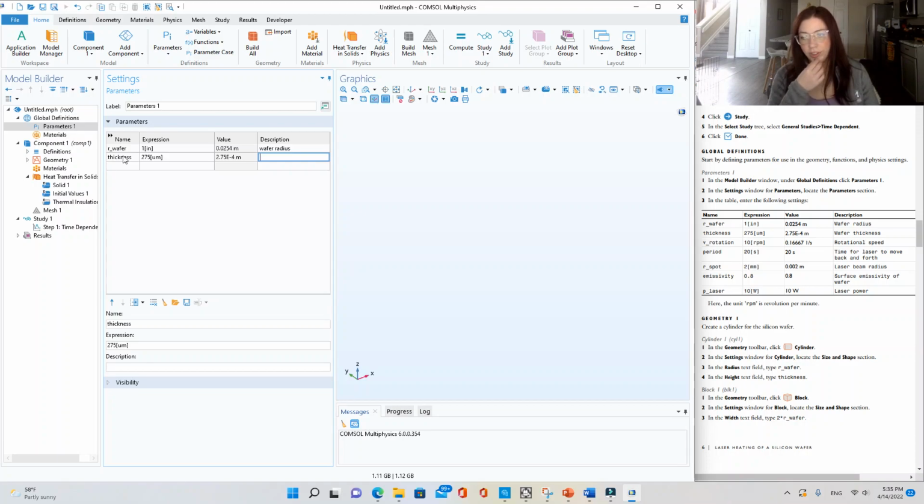That is a very thin wafer. I think the wafers we used at the fab I was in were nominal thickness ranging from like 625 to 675, and anything thinner than like 500 microns was considered thin. So 275 micron wafer is extremely thin.